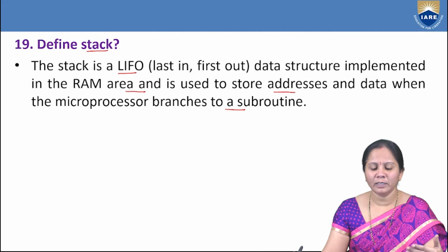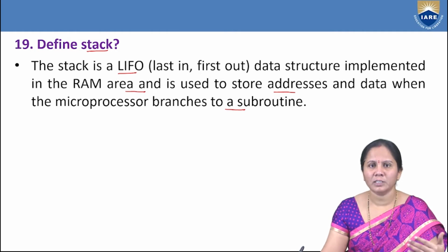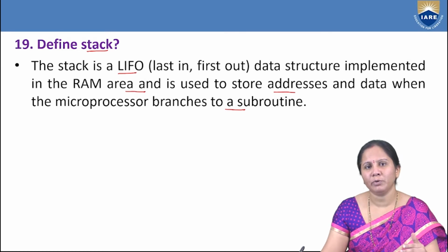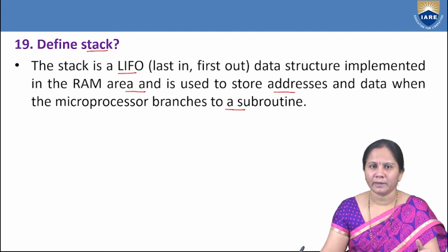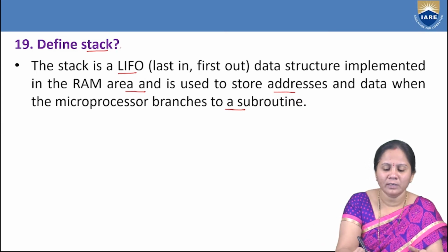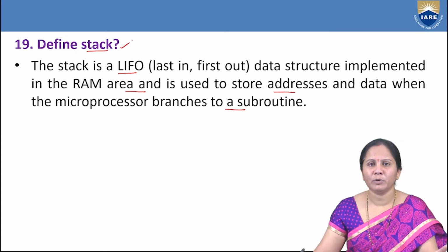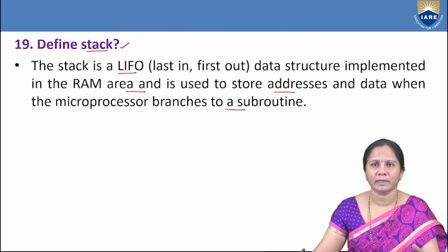Generally during subroutine execution, we use push and pop instructions. Before executing a subroutine, it has to store the contents on the stack, and after executing the subroutine, returning to the main program, it has to retrieve the contents from the stack. That is why the information of the subroutine is stored on the stack.